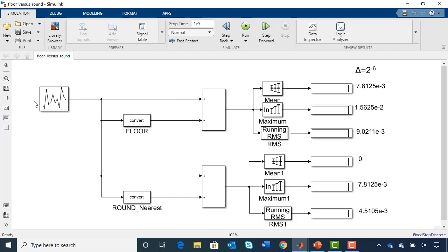Okay. We're just going to use some sort of random source. And we'll take the quantized value and we'll subtract that from the known right answer. And we'll do it once with a round to floor and once with a round to nearest. And over here, what I've done is written the predicted values based on the theoretical derivations from the last slide. And we'll go ahead and give that a run.